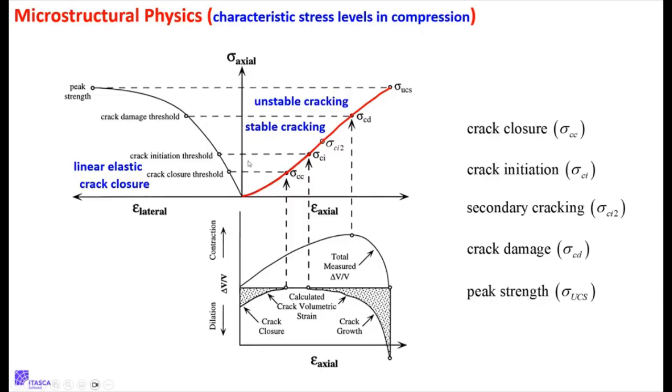Let's just start with the beginning here. So you start squeezing the rock specimen. And notice it starts stiffening like this. Stiffening means the slope gets bigger. Then the slope stays straight. Now, have we seen this before in the stuff we've done for granular systems? What do we see in the granular systems?